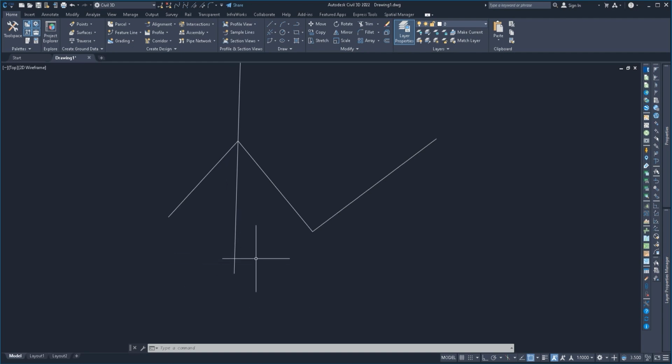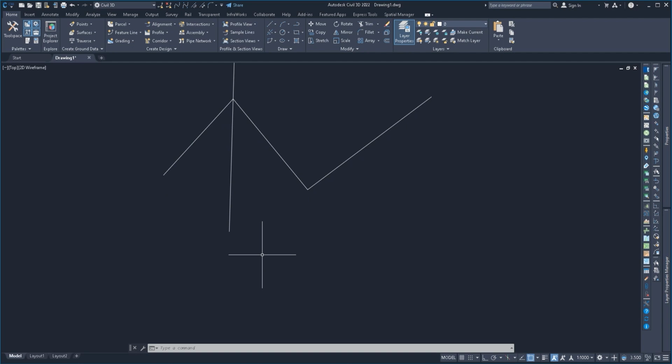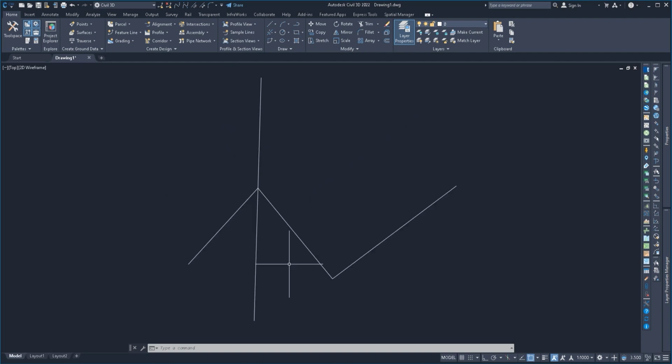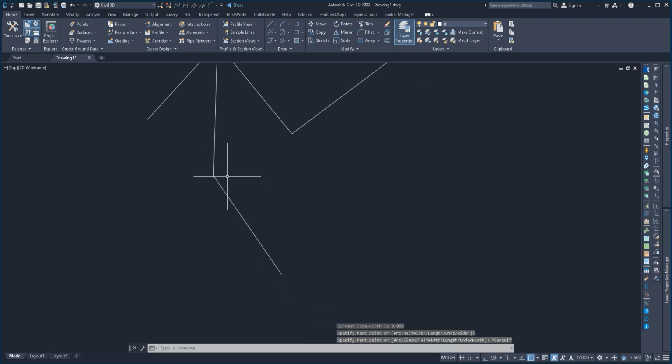And similarly, if we have a certain slope below our guideline, then we can know in advance how our pattern is going to relate to that slope, so we can make any necessary changes if we have to. The other thing that the trajectory allows us to understand is how many patterns we need to cover a landscape. So for example, if we have a slope that follows only a single general trajectory, then we know in advance that we only need one pattern to tackle that landscape. But if all of a sudden the trajectory of the slope is shifting in direction, then we know that somewhere at this point we're going to need to break our pattern and start a new one.